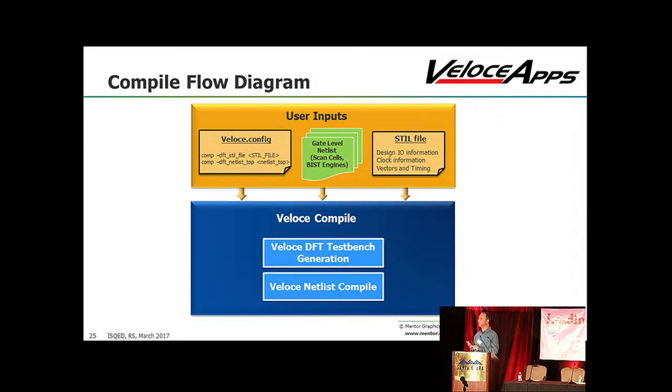It contains the vectors, the input zeros and ones, the outputs H, L, and X's. It also contains timing information, whether it's a clock or data, if it's a return format, a non-return format, or a surround by. So you take that pattern, that's what's going to get run on the tester.